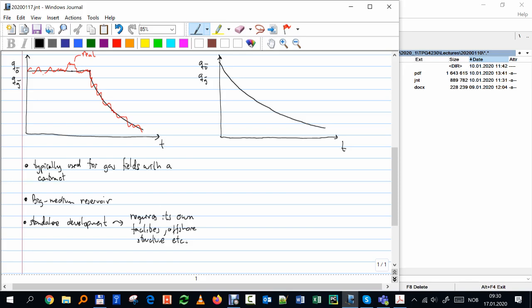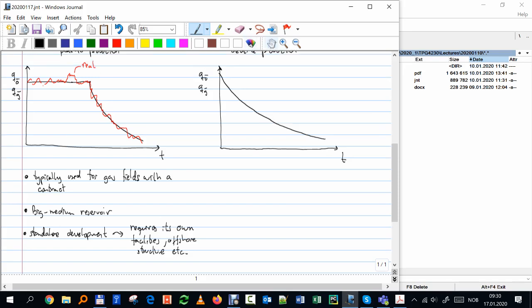And we are going to go a bit into the economics. I'm going to give some comments, but basically, if, for example, you make a platform, I have to build my facility to process this amount of oil and this amount of gas. If I try to operate in decline mode, that facility I built would probably be used at capacity only for the first second of the first year of production, which really doesn't make much sense. So if I make standalone facilities, an offshore structure, a big investment, I want it to be operating for a long time at that capacity.